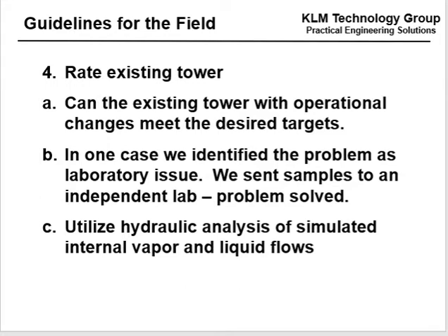Rate the existing tower. Can the tower with operational changes meet the desired products? In one case, we were able to match the heat and material balance. We were able to match the current operations, but we were not able to match the product purities. Went and did some other research. It was pretty close to the things I found in the field. So we sent the samples to an independent lab, and the independent lab was able to verify that the product purities were being met.